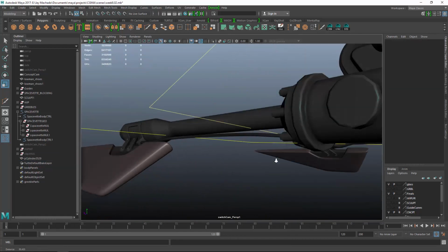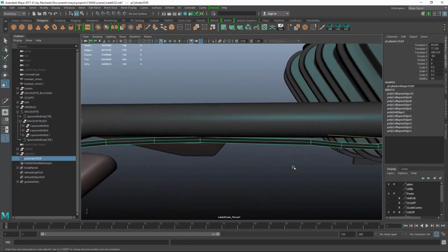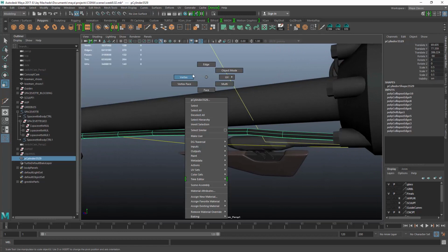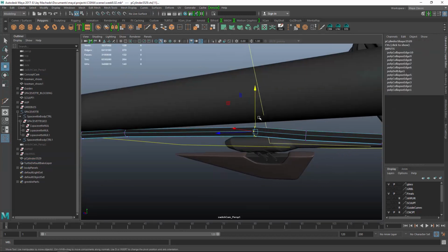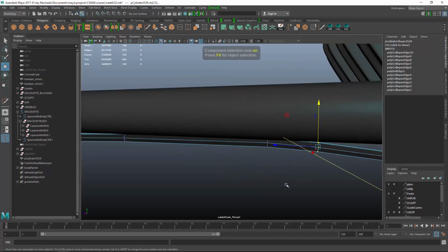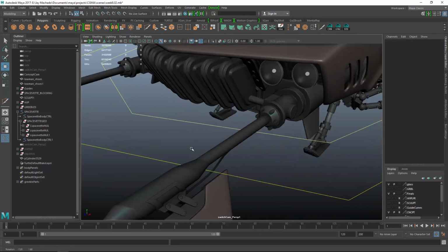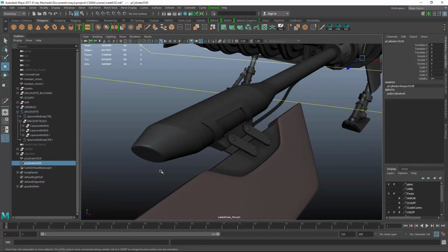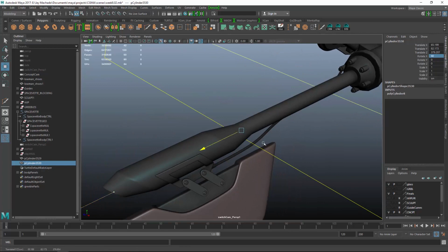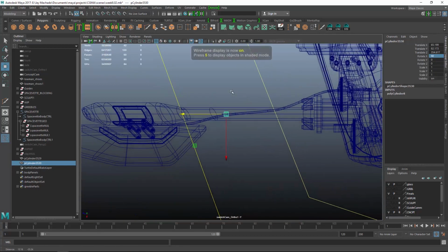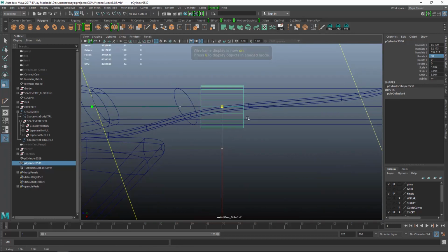The other thing that's kind of important to selling these sort of curves and whatnot is actually creating some clips. Let me move this up a bit, and then I'm going to move this also. Wires are almost never left hanging like this. So what I'm going to do is create another cylinder and snap it to the front here. And then we'll go ahead and rotate this 90 degrees. And let's go out this way. And let's just scale this thing up, and scale it in quite a bit.